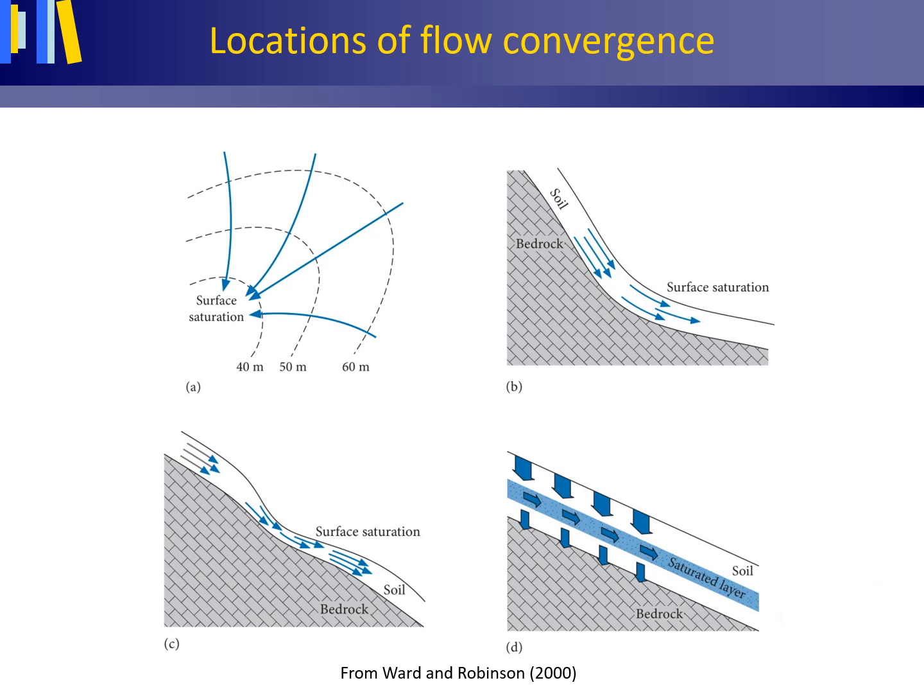In conclusion, the process of a rising water table reaching the land surface is a very important mechanism for the generation of saturation excess overland flow in humid climates. The saturated areas where quick flow is generated, with saturation often occurring from below as just explained, are called variable source areas or partial areas.